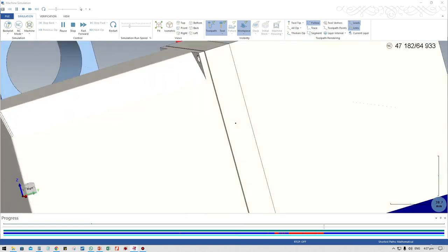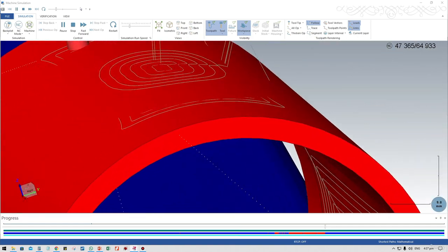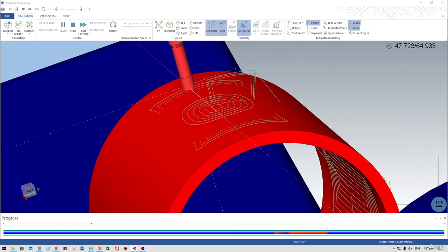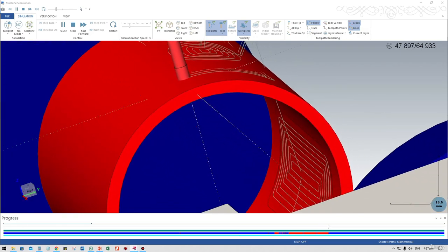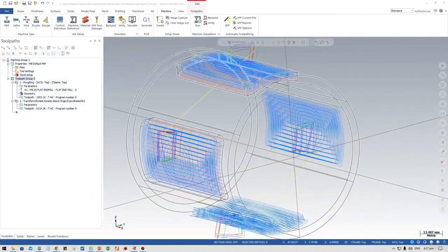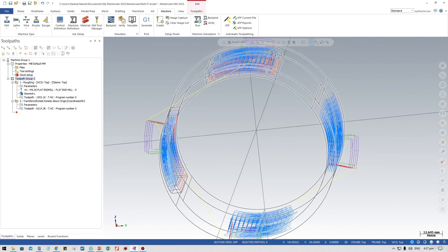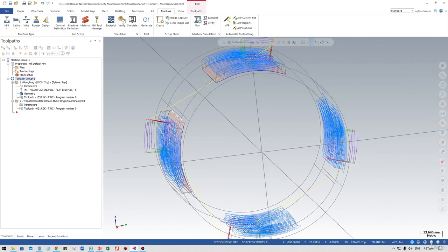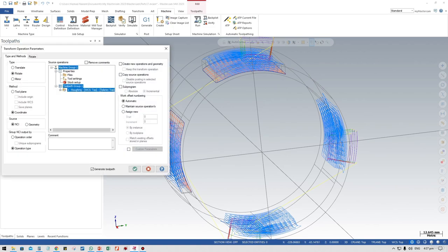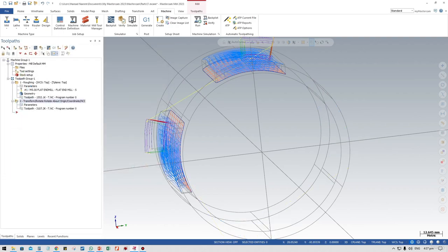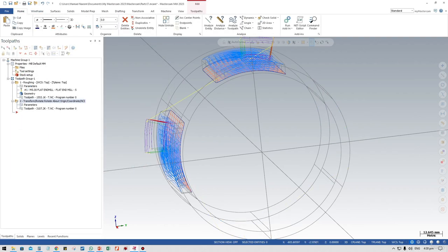This is because you see that this color line represents that the tool is being transferred to another position and collides with this workpiece. So for that purpose, you need to create a link between that. So you see here this link. So this link definitely touches down the workpiece and causes the collision. Okay. So let's go to parameter, and what I'm going to do is make it 2. Okay. And go to home and unblank.